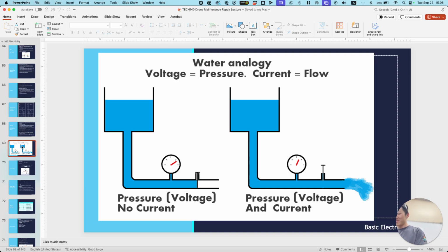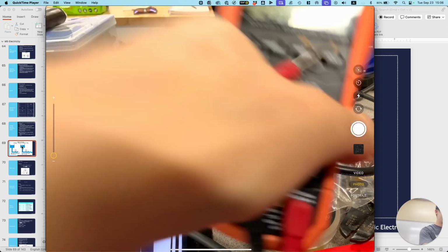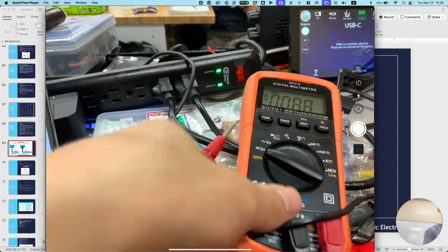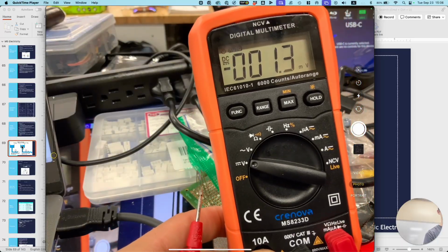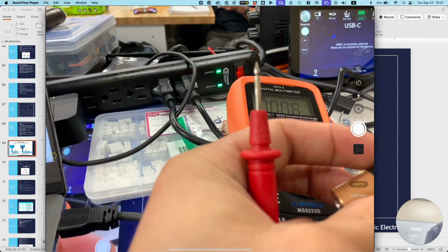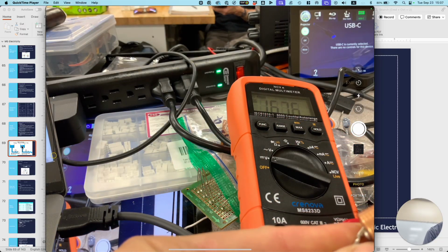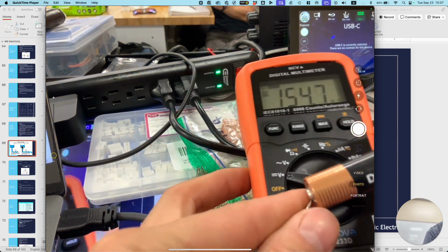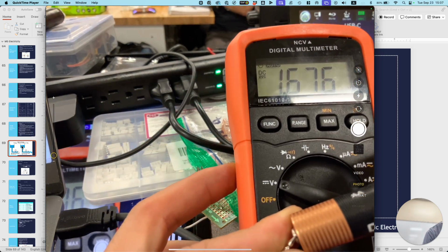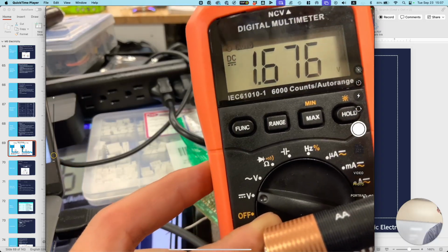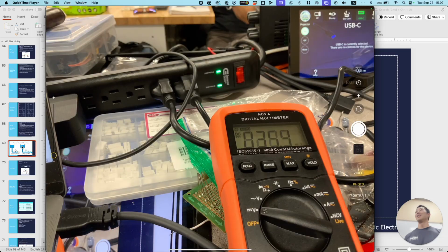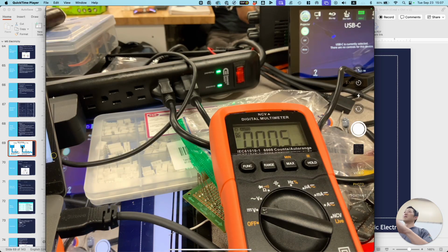Okay, so if we go here, let's see. This is a fresh battery. Once again, is this AC or DC for a battery? DC. Okay, I'm going to put negative to this side. This is how you actually measure it. You see right here, it says 1.6. That's what I was saying earlier. This is a really fresh battery. Nominal is 1.5, and usually when it starts to die, it's like 1.3, 1.2, and then it's usually not usable. You notice how it doesn't go to 0 to be dead in terms of devices. It just goes below a certain point.